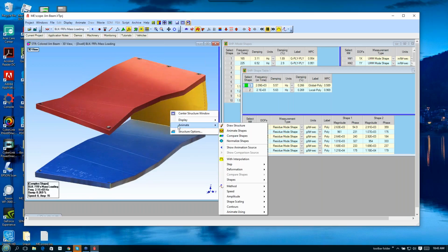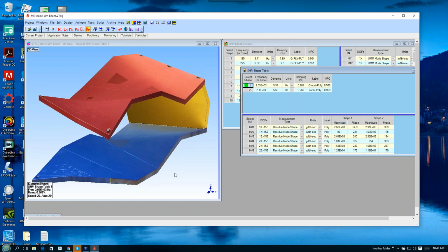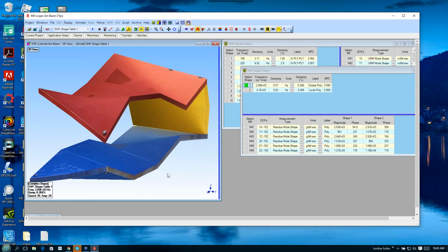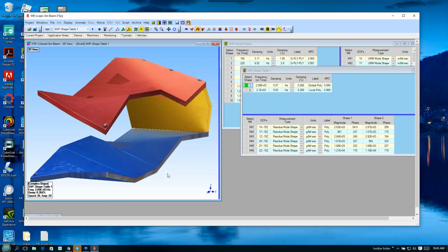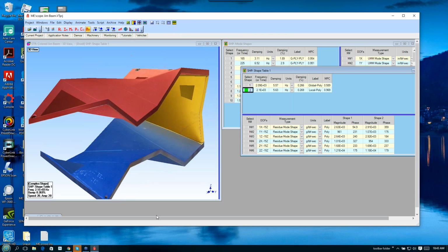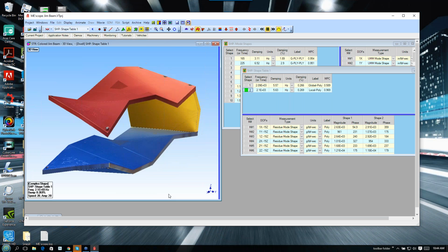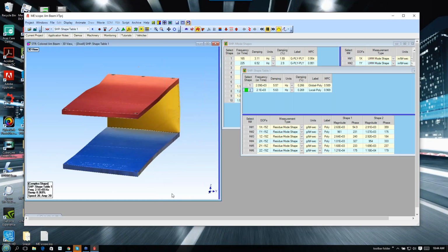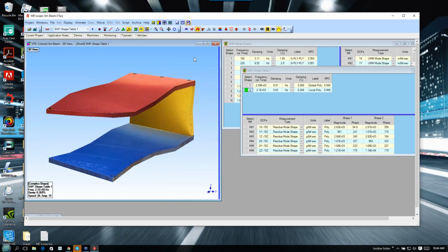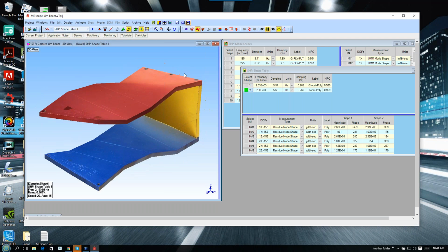We're not normalized, so you can see that mode shape has so much complexity in it, I don't expect to see that from a lightly damped structure, but that's what the global fitter gave me. Here's what the local fitter gave me, a much cleaner looking mode shape. So again, looking at the animated picture is a good way to judge whether your curve fitting results are acceptable or not.